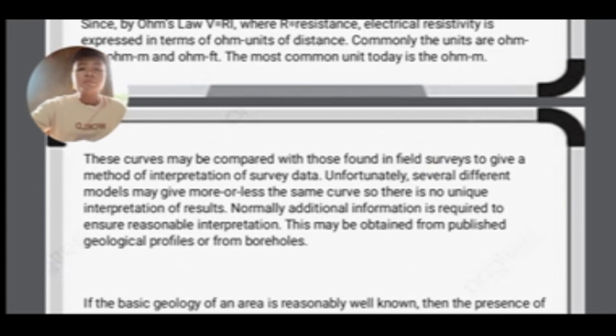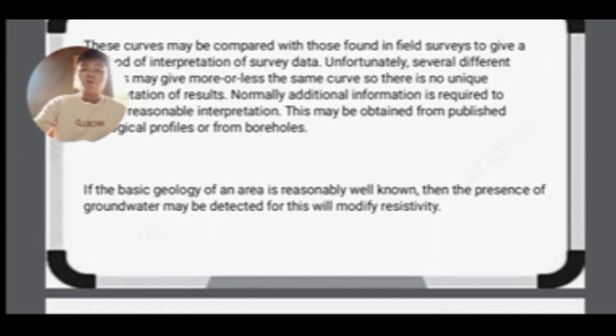So these curves may be compared with those found in field surveys to give an interpretation of the subsurface data. Unfortunately, several different models may give more or less the same curve, so there is no unique interpretation of the result. Normally, additional information is required to ensure a reasonable interpretation. This may be obtained from published geological profiles or from boreholes.